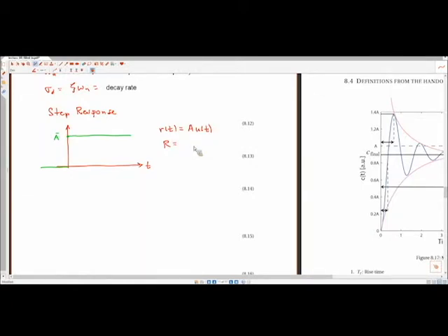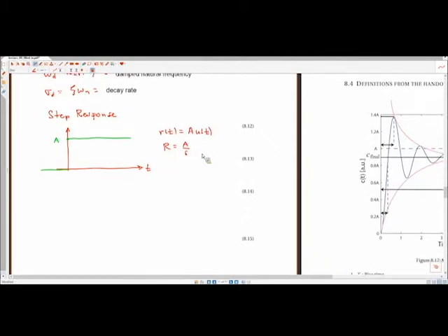Okay. And then I'm going to skip the next steps because this looks a lot like some of the homework problems we've done thus far. So this is the case of a second order underdamped system with an extra pole at the origin, and then we're doing the inverse Laplace transform of this. We saw this on homework 5, right? And we've seen this in a few different locations as well.